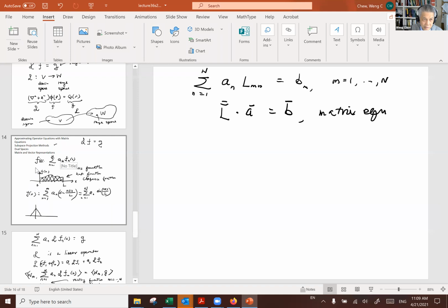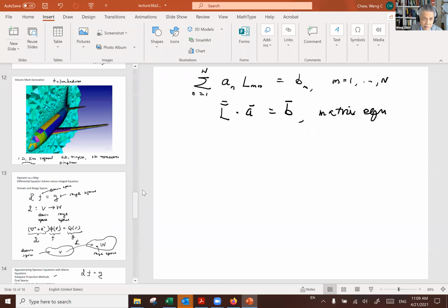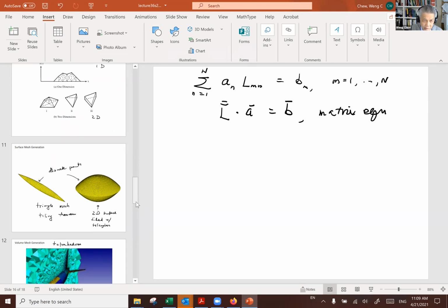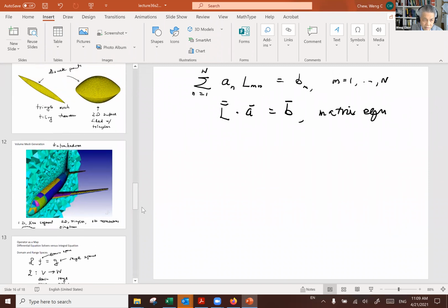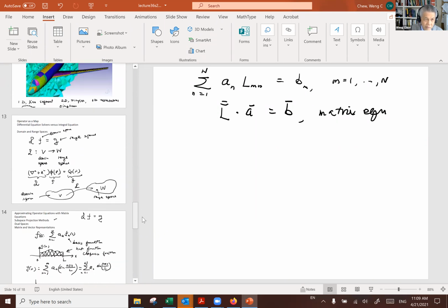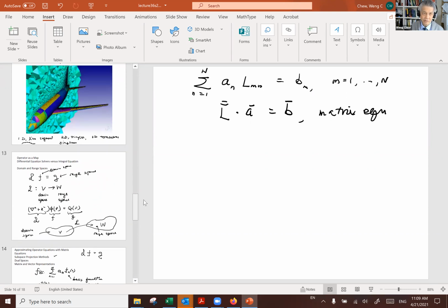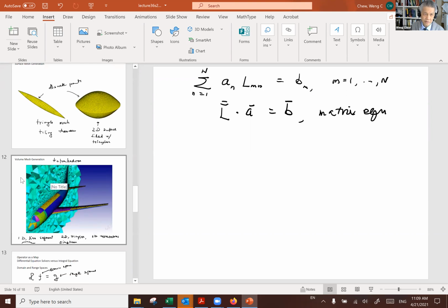If this function is a two-dimensional function, you will use triangular meshes and define your basis function on the triangular mesh, or you can have this repeated for 3 dimensions. Then there you will have to define your function in 3 dimensions using a 3D tetrahedral mesh and so on.